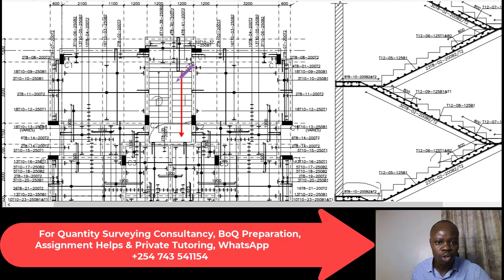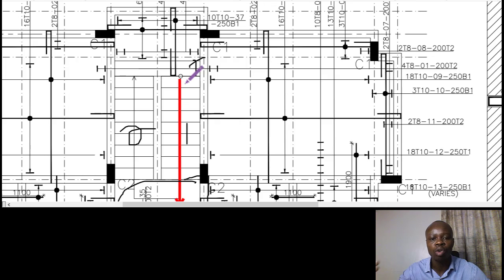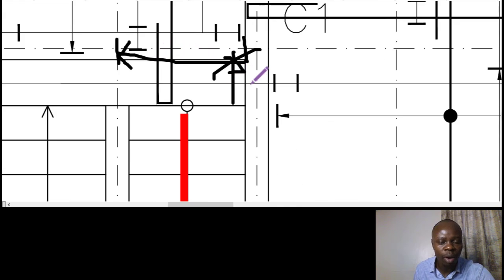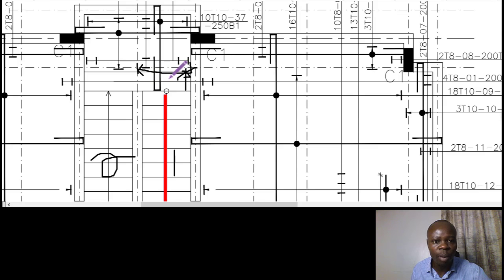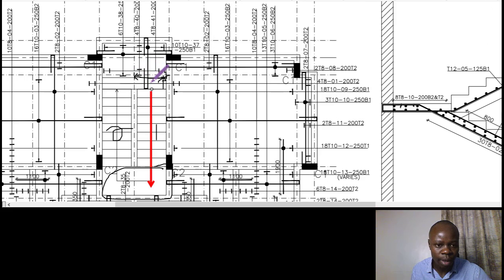when I told you when it's across, when they have been shown across, it means when they're showing you at the tip of the bars, as they are showing for the thicknessing, then they have been cut across. It means what we have at the thicknessing is spanning from this point to this point. Just check on my arrow. This is the span where we have those reinforcement bars for the thicknessing, and there are 4 of them.